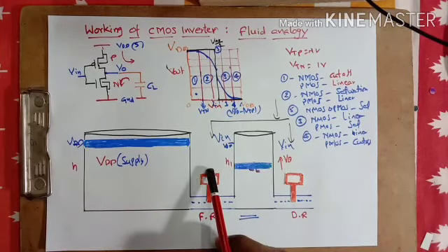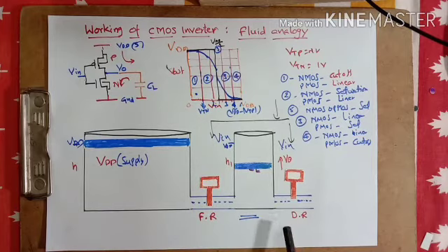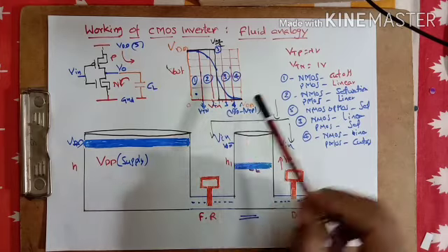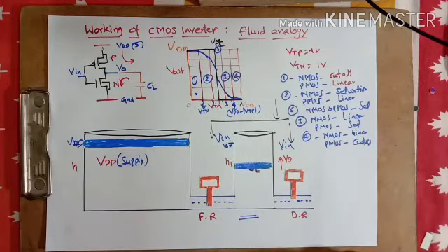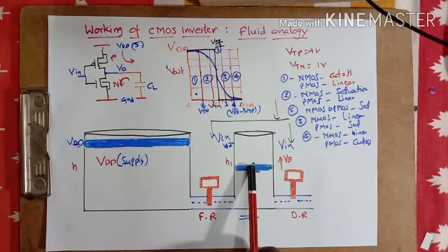So when the left gate is closed further a little and it is opened a little out there, which is now equivalent to applying 3 volts on this, what is happening here? The filling rate is supposed to be less and the draining rate is becoming more here. Now here, because it is opening less than halfway through, the filling rate of the water does not depend upon the height difference. So filling is constant, the rate of filling is constant.